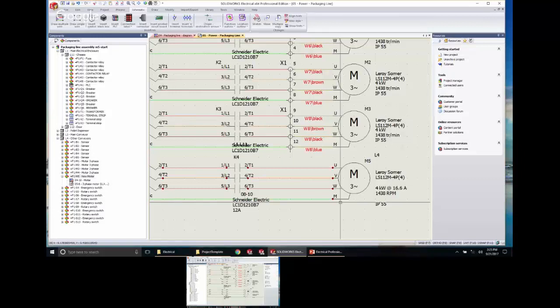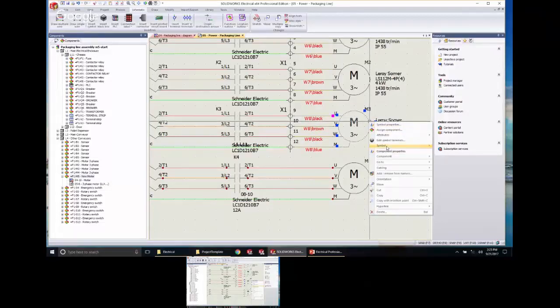And that gets back to a basic thing with SolidWorks Electrical, is that it goes off the as-built kind of style. It's not going to change anything until you say, I want this changed this way. You'll see a lot of these places, if you did change a symbol or something, you always have to go in here, right click, go to the symbol and say update.